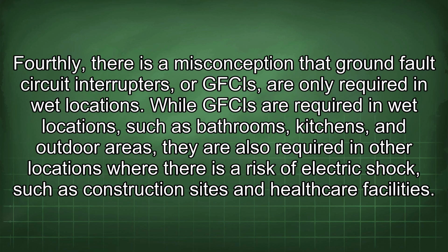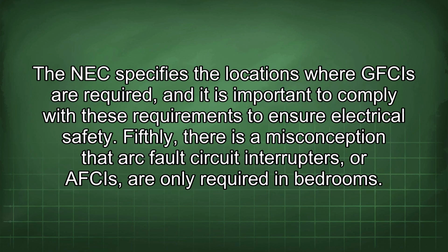Fourthly, there is a misconception that ground fault circuit interrupters, or GFCIs, are only required in wet locations. While GFCIs are required in wet locations such as bathrooms, kitchens, and outdoor areas, they are also required in other locations where there is a risk of electric shock, such as construction sites and healthcare facilities. The NEC specifies the locations where GFCIs are required, and it is important to comply with these requirements to ensure electrical safety.